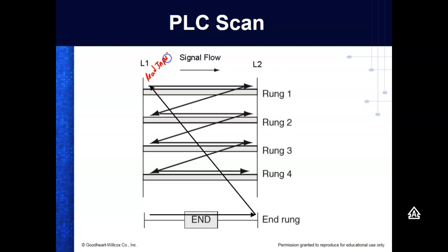Read inputs. And right here it's doing what? It's running the logic, running the program. And then it does what? Yeah, updates outputs.